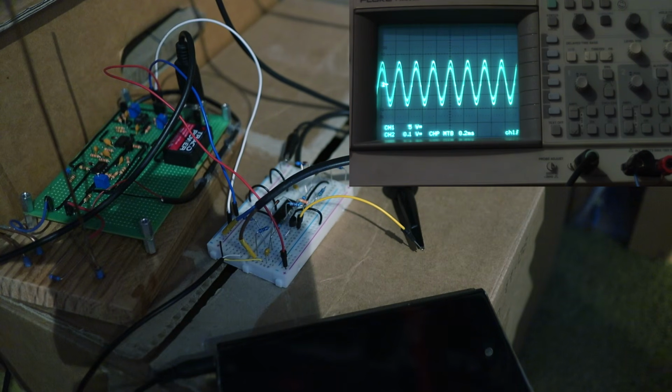So you have to make sure that your attack time is fast enough so that it's practically usable and it doesn't allow the volume or the amplitude to rise up way too high and cause all kinds of problems. But also you want it to be slow enough so that it does not respond to individual cycles of the signal and only to the overall amplitude.